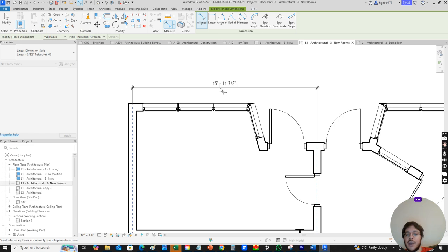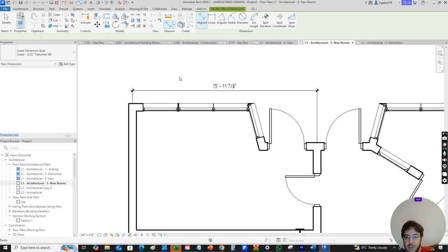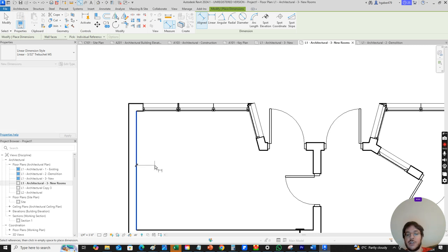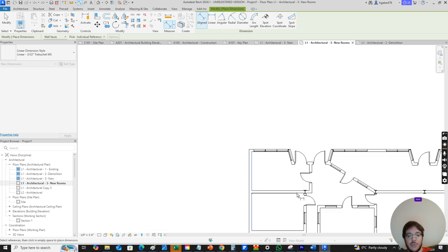You end up, somebody tries to build this wall on this line. They don't know how thick this wall is. So what you're better off doing, and you can move this line, but it's not easy to move. So I'm gonna undo this, and what we're gonna do actually is we're gonna measure from the interior edge of the exterior wall to the center of our next wall.